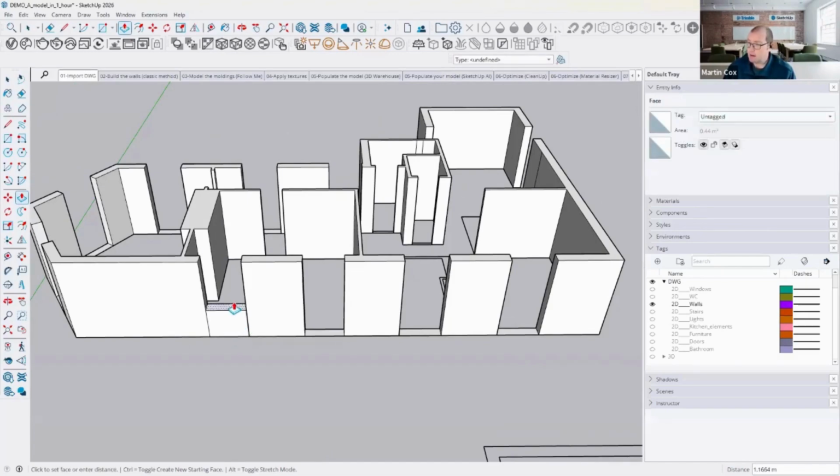For my windows, I'm going to choose 48 centimeters. So instead of meters this time, 48 centimeters. I'm not going to go all the way around here in the interest of time. But now, we're building the bottom of the walls. With push-pull, if I push-pull that top again, we can see that it's moving that bottom wall. If I tap Control, it will create another wall for me.